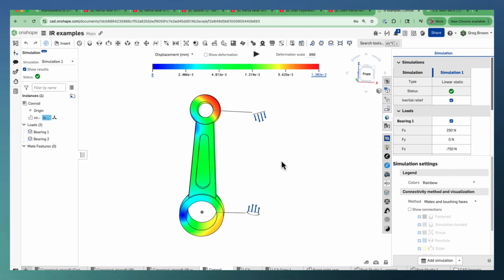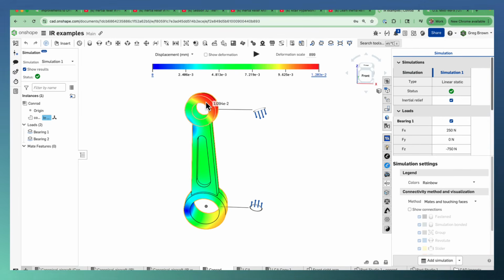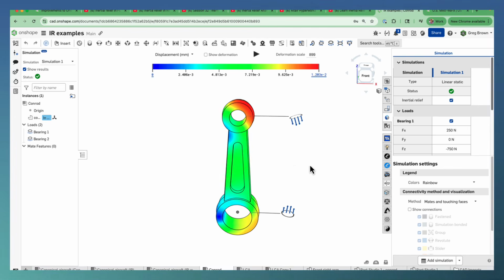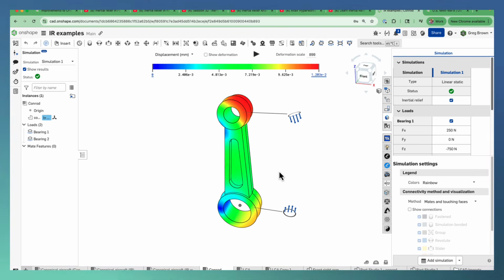Now, it's not applicable if the frequency of change of these directions is at the resonance frequency or the first fundamental frequency of the part. This doesn't take the place of a true dynamic analysis. It turns something into a quasi-static analysis, as I said, which is a much, much simpler problem to solve. And certainly, if you are away from those fundamental frequencies, then it's a valid use of this type of technology. All right, so that is with this free situation. Normally, this thing has 6 rigid modes.